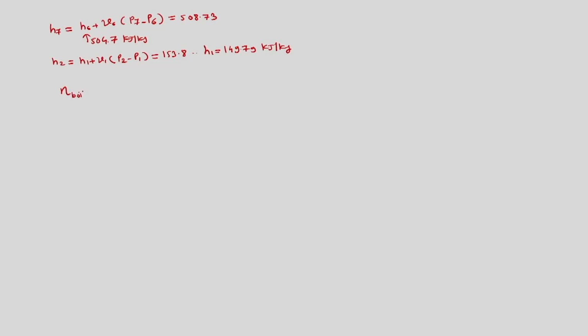So boiler efficiency is given as 88%, which is basically Q in divided by mass flow rate of fuel into its calorific value. Basically we have to find out Q in over here. So Q in is basically m dot minus m dot B, the mass flow rate of the bleed, and this mass of the steam is getting heated from 2 to 3, and then only m dot B gets heated from 7 to 3.